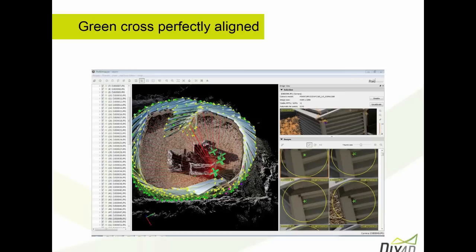So to summarize, the benefit is that by visualizing the tie point, you can first assess if the reprojection is good and is at the right spot, which means that the calibration is very likely to be good, and it helps you to detect areas where you can visually see that the tie points are not matching. In addition, it allows you to add your own manual tie points, which are taken into account when you're doing a re-optimization to really adjust and take your measurements to resolve the ambiguities that happen during the processing.